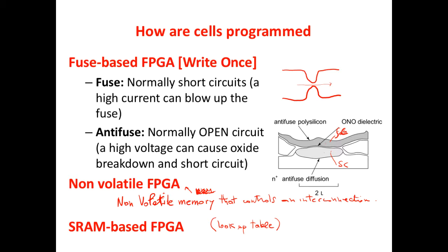Okay, that's it. There are many FPGA that are sold in this way. This means that from the design point of view of the FPGA, you need to put a lot of interconnections, and then during the program operation, one needs to open all the interconnections that one does not want. Okay? You need to consider that this is typically done automatically by a specific software.